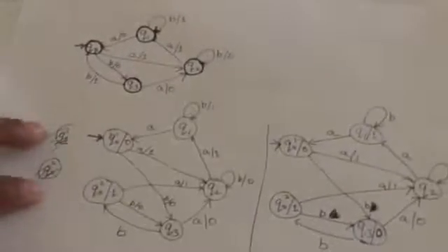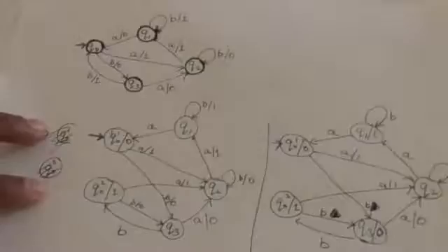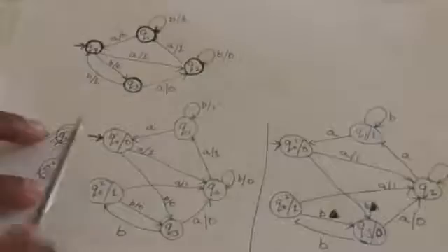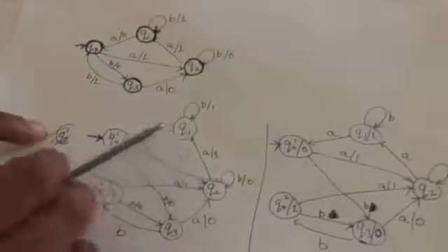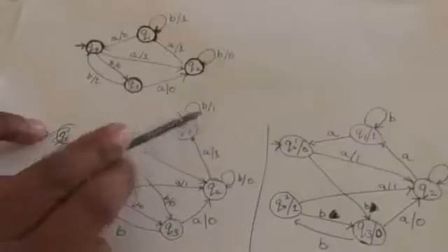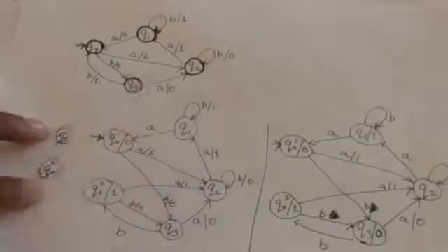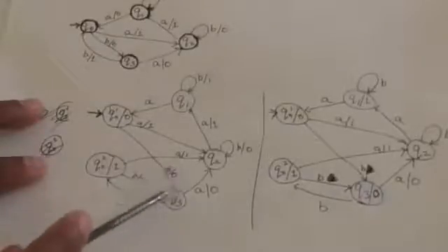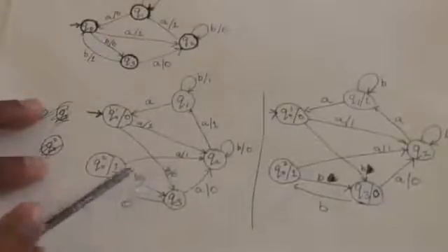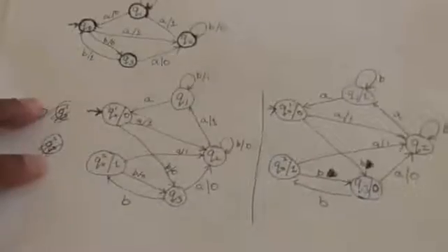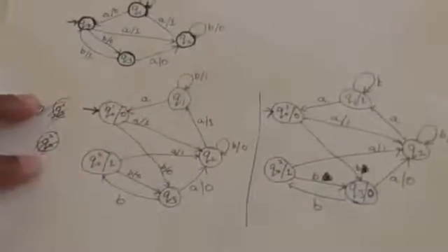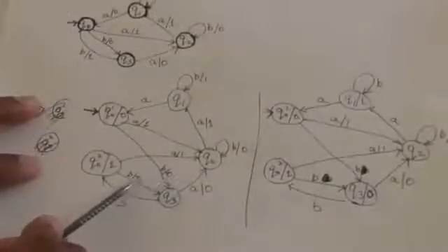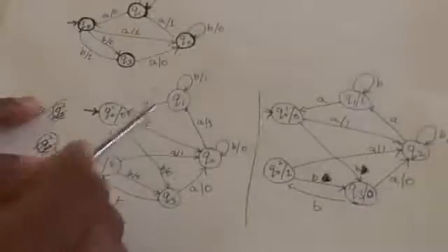Now look at this machine. We have to transform other states also. Now Q1 and Q3 state. Q1 has two incoming edges. Both are labeled by output symbol 1. Q3 also has two incoming edges which are labeled by output symbol 0. So what will we do? We will remove output symbol from incoming edges and associate it with the state.